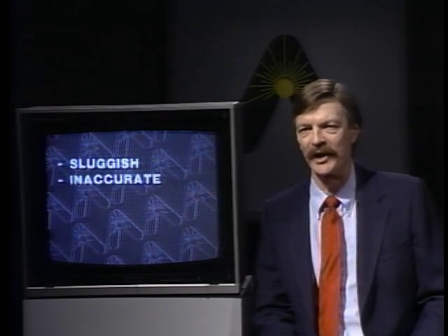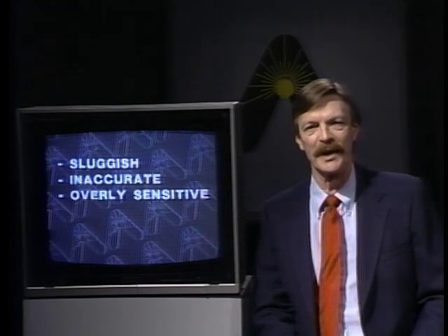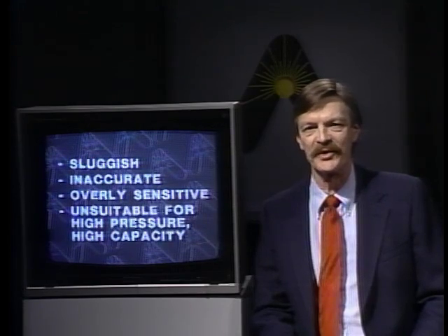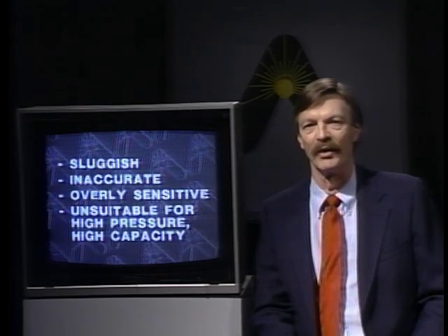No matter what fluid is being controlled, the flow dynamics of a single-seated unbalanced pressure valve make it sluggish, inaccurate, and sensitive to inlet pressure variations. Additionally, the pressure imbalance makes them unsuitable for high pressure or high capacity service. For liquid service, where tight shutoff is required, the best choice is a single-seated pressure-balanced valve. There are two possible designs for these valves, but both of them are suited only to open with the flow.